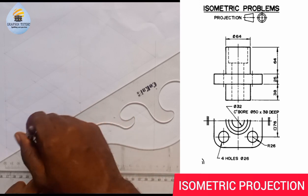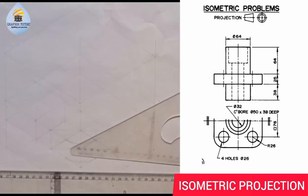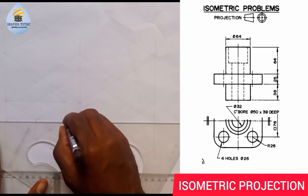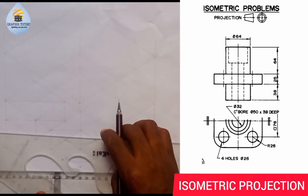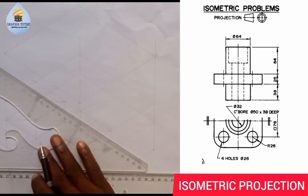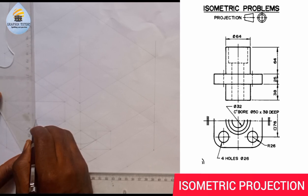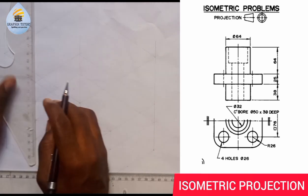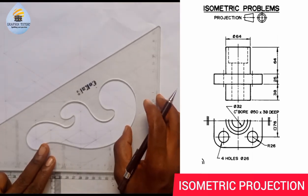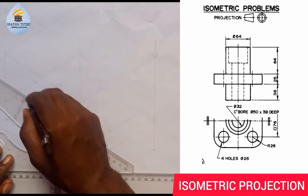So what you just simply need to do here is, what you're focusing on is this point here. So I'll just join my diagonal this way. Join my diagonal this way. Right? Then I need to get the center line. I can use this as a help to get the center point, or I'll just join the diagonal here this way. This will give me the center here. That is the center. So if I have the center there, I just have to draw a vertical line across and also a horizontal line too across this way.